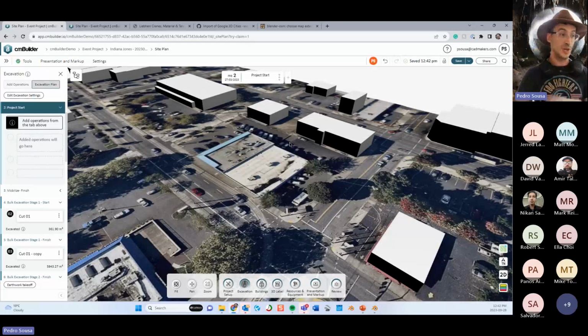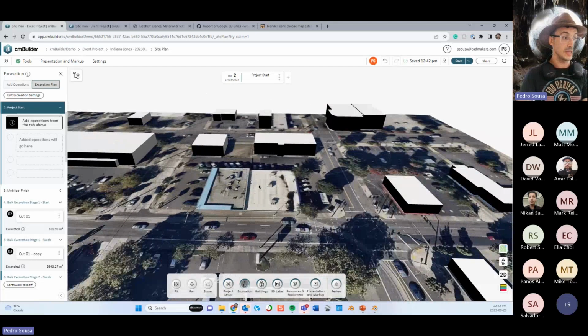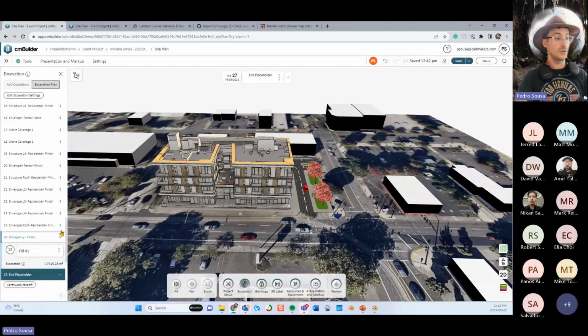Anyways, so this is a good way for you to have locations to store adjustments or parts that you're not using at the moment. Sometimes I even put a lot of these parts over here into a placeholder milestone in the end so I can deal with them later and remove them from my view at the moment. So there are a lot of things that you can do with that, right? So if you were creating, for example, a massing that is a template for a sketch that you're going to keep projecting down to create sketches, something that I already showed in a previous workshop, you can store that massing into one of these placeholder milestones so they won't show up on your simulation.